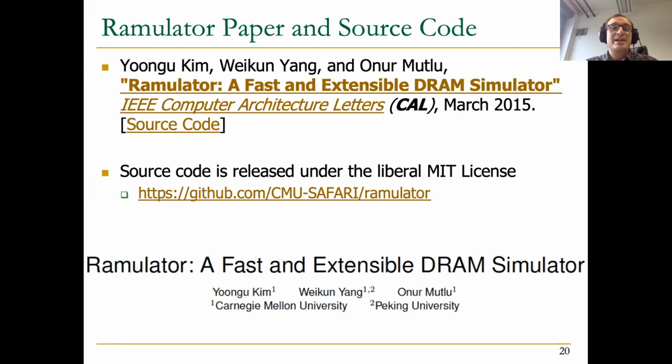But there's a golden model for memory control that's released by, let's say, a company that's respectable, and we verified Ramulator against that golden model. Is it really doing the scheduling right? Is it really obeying the timing parameters? Basically, all of those were verified.